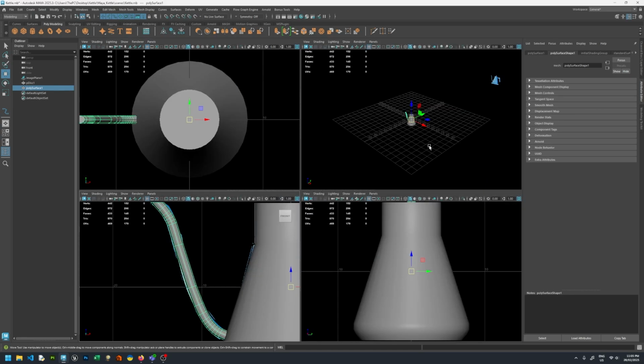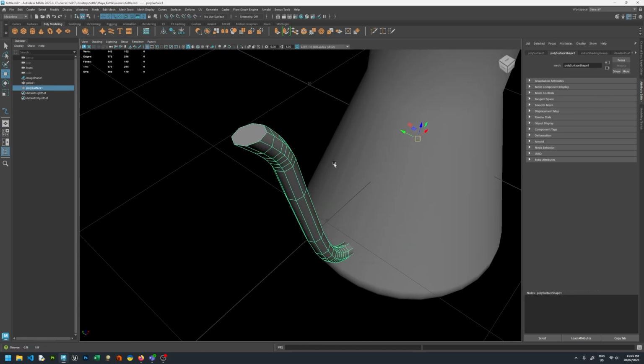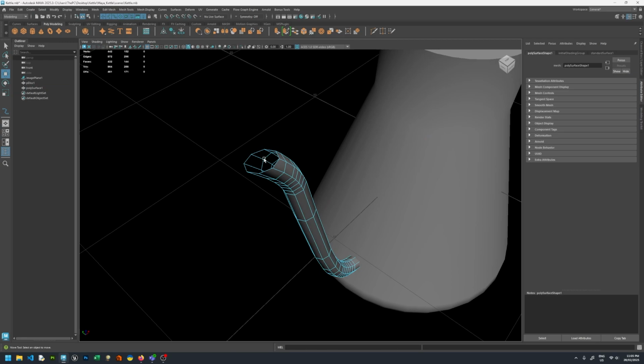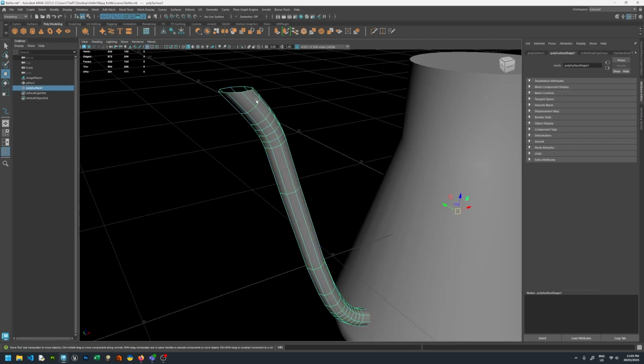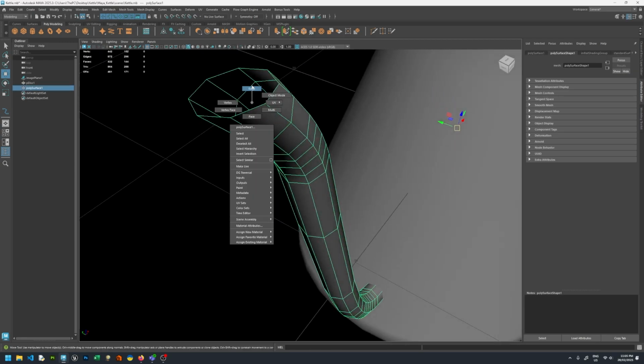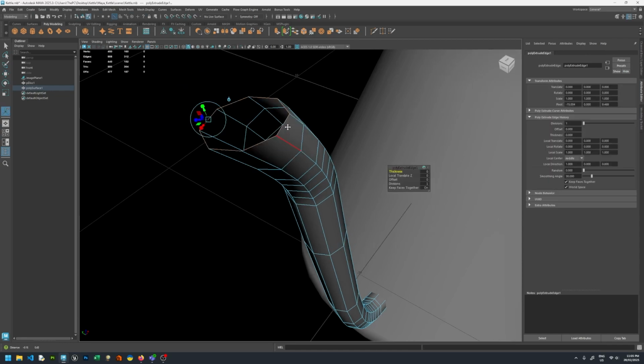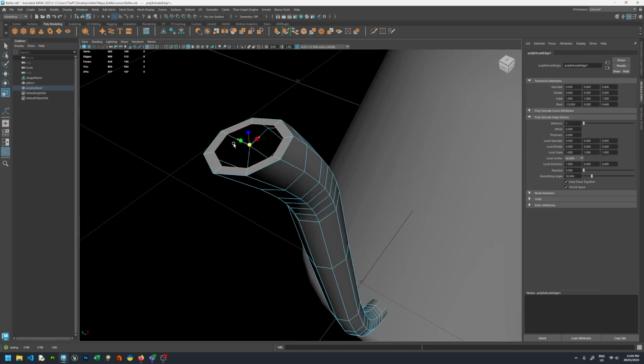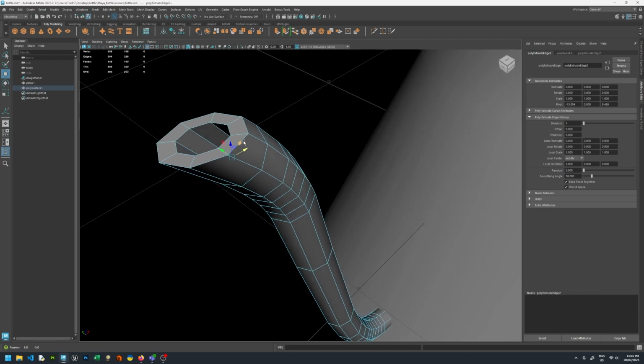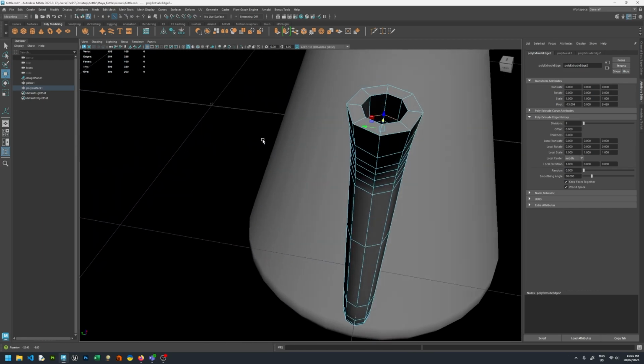We've got that baked in now. And that'll give us a face, which we don't need. And this is a hollow tube now. But I do want to extrude the top so we don't see the back sides of faces. I'll extrude it inwards and then extrude again and pull that edge down in the tube.